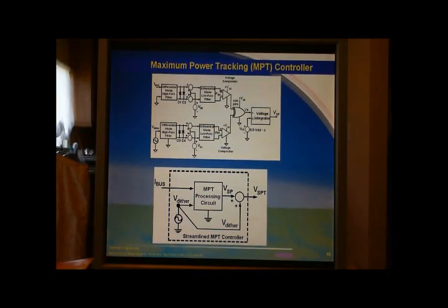These two signals are processed in parallel with the same transmission delay, go to their respective low-pass filtering, and extract their AC information or AC signal without including their DC operating points.